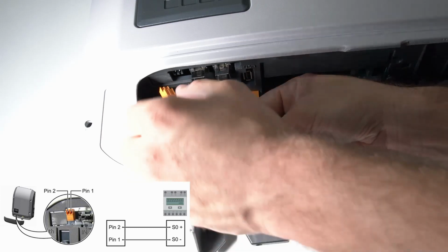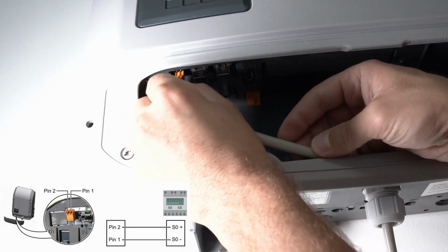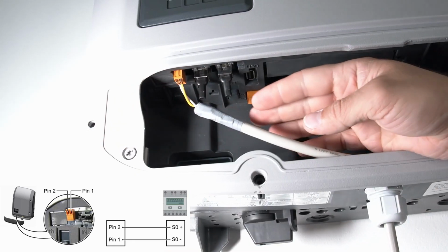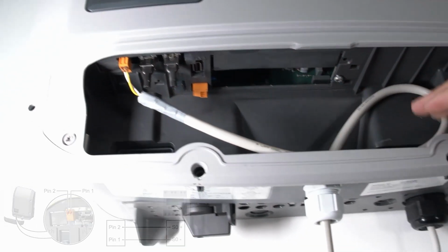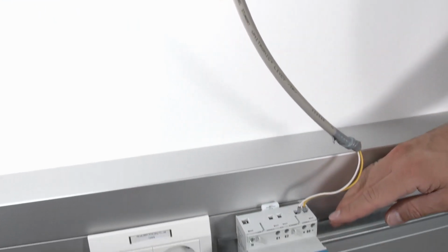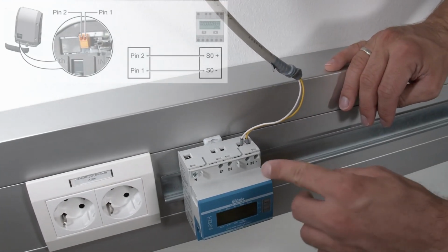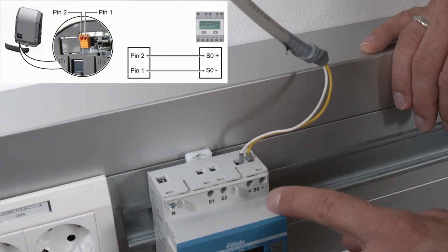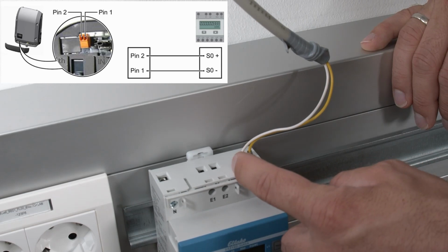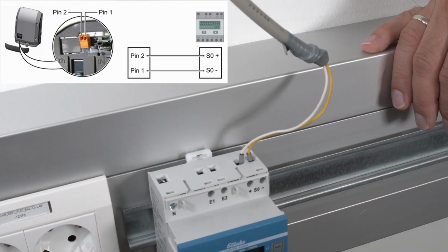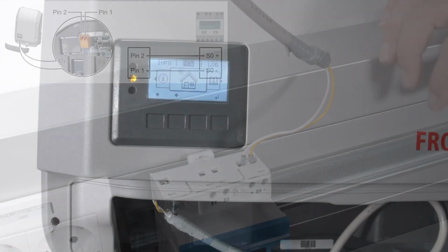After connecting the two cables, we can plug the signal input back into the inverter, and then we go directly over a cable communication line down to the S0 meter. Here on the S0 meter we again have S0 minus on the right side and S0 plus on the left side, and with these two cable connections we can directly go to the signal input of the inverter.